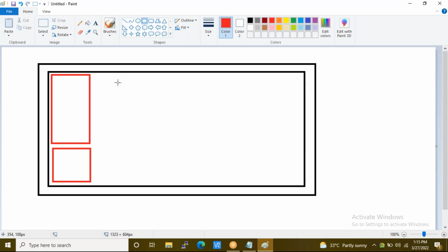In floor plan, we place the macros, effectively utilizing the area. Next is power planning, distributing the power all over your design area for more effective power. Next is placement.